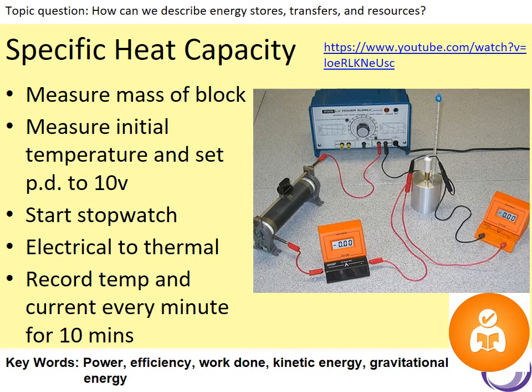So you will need to understand how to carry out this specific heat capacity required practical. In the diagram you can see a setup of this practical, and there are a few things to consider for this. I put the main key points on the left for this practical that you would need to know. So what you'd start off with doing is you'd set up your equipment, but also you would need to know what the mass of your block is. So usually we'd maybe use a 1 kilogram block.